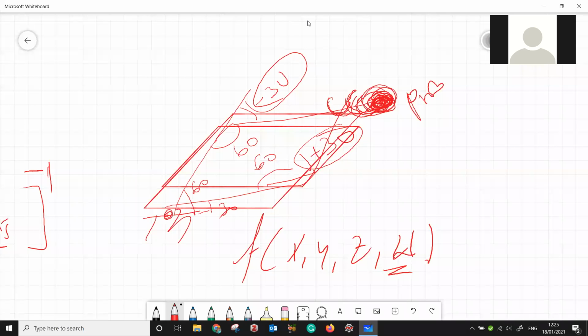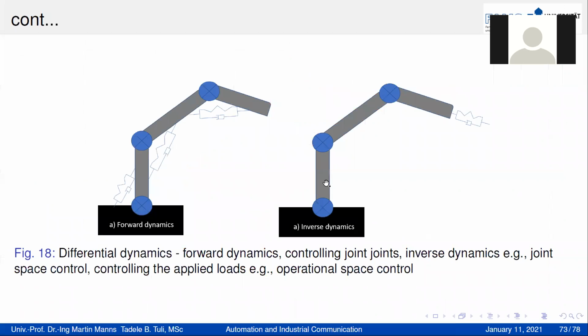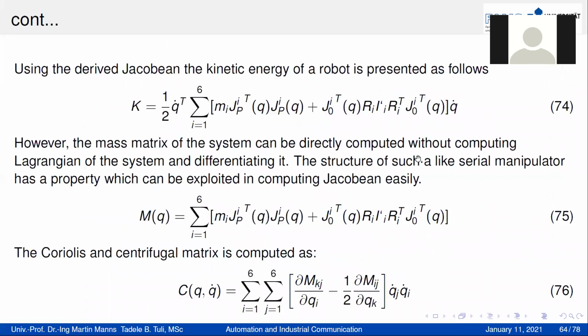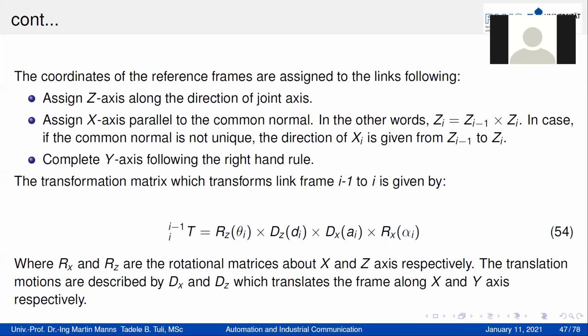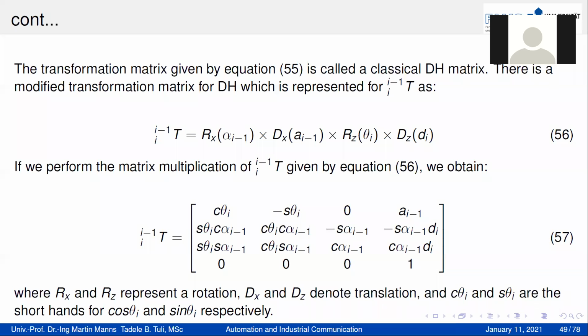Quaternion is an imaginary space. It is complex. It uses complex numbers, or it uses an imaginary axis. It takes from the x, y, z into a different hyperplane. But the Euler uses the Cartesian space, and then it will compute the rotation about each axis. But quaternion uses a hyperspace to represent the rotation and the magnitude. That's the difference. Actually, if you are interested, there are mathematical representations in this lecture, so you can look at that. That's all about today's session regarding the kinematics.